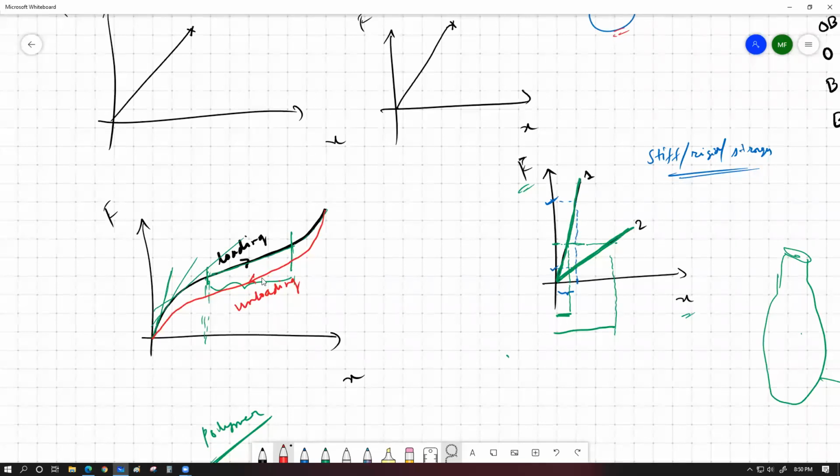Now, pretty much like earlier, have a look: polymeric substances behave like this. And the name of this behavior of following two different paths, one while loading and another one while unloading, is what we call hysteresis. This behavior of having two different pathways while loading and unloading is called hysteresis. And this loop that you can see over here is what we call the hysteresis loop.